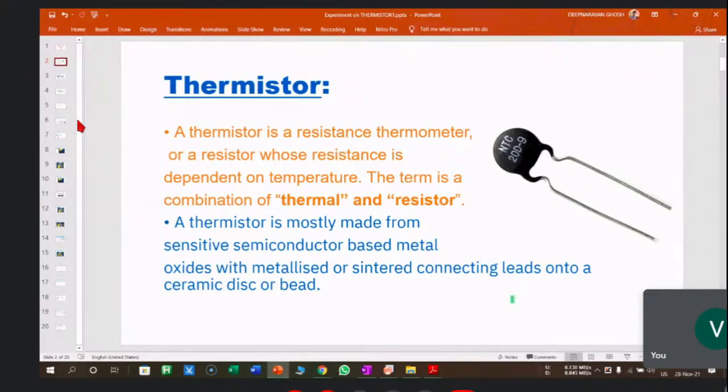My question is, suppose I get the calibration data from a thermistor, and I use that calibration graph with another thermistor. Normally there will be deviation. I understand, yes, sir, there will be deviation. What is the extent of deviation? The point is, he has not checked that. He has only one thermistor with him.